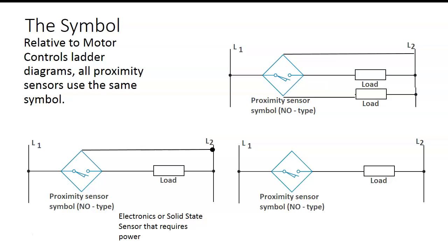And then we have a 4-wire sensor. This is similar to something, right? It's simulating. This right here is not a switch. It's usually a solid state device like in here. It'll be a triac or it'll be a relay. Some of our sensors have relay output, so you can actually hear them click when they become true.